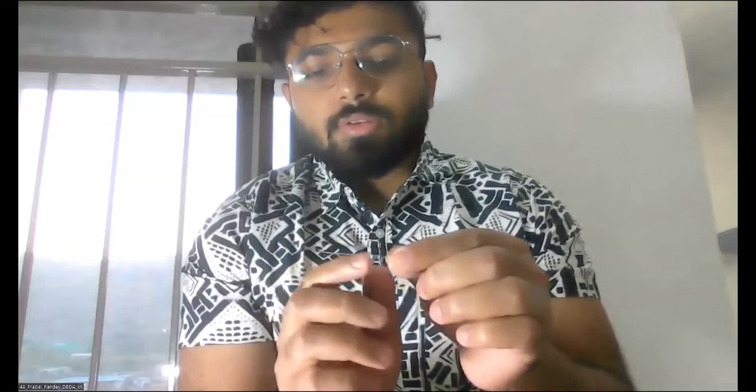So these three colors symbolize the value. The first color represents the first digit, the second color represents the second digit of the resistance, and the unit of resistance is ohm. And the third color, when converted into a digit, gives the power of 10. So here, the first color is red. Now, to remember the code of the colors,